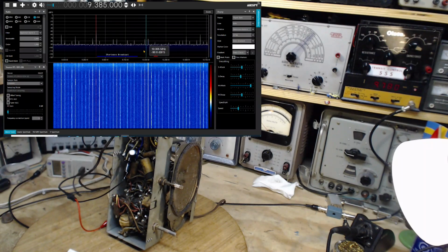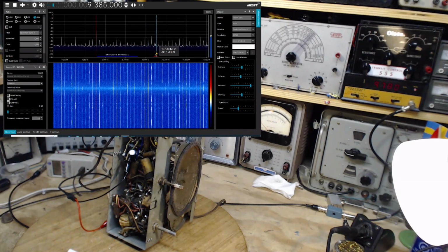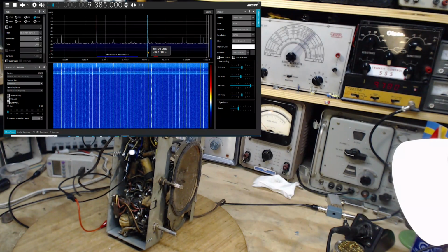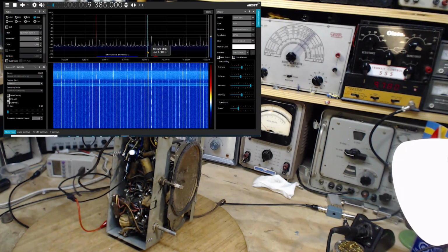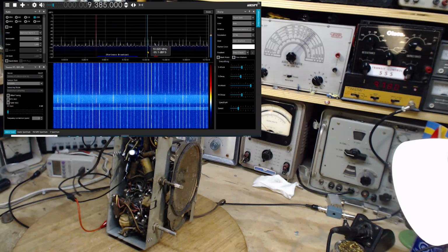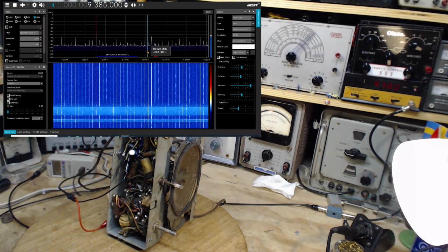No, that doesn't make sense at all. What I just did, that doesn't make sense. Radio's tuned, let me get this straight now. Radio's tuned to 9780. So we take 9780, add 455 to it. Local oscillator should be at 10.235.